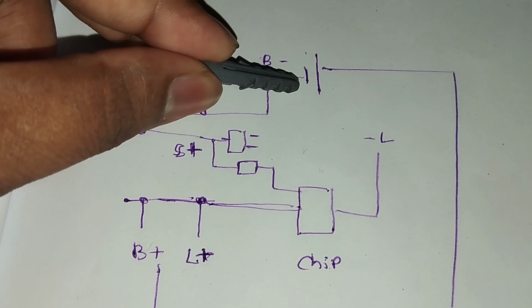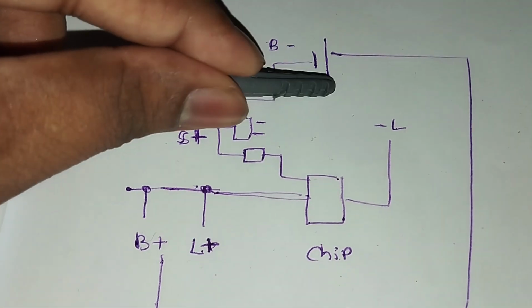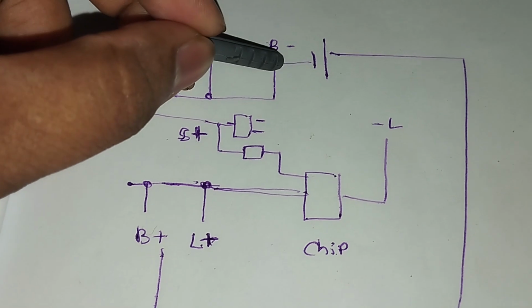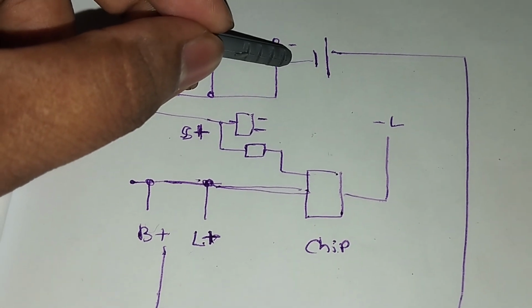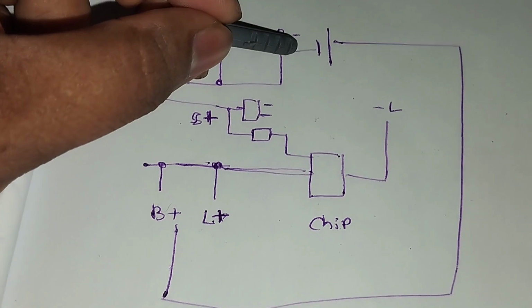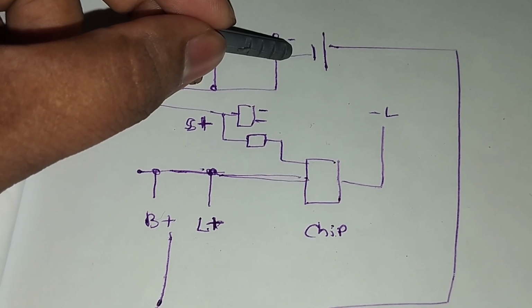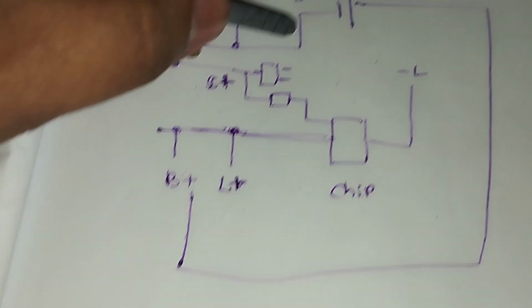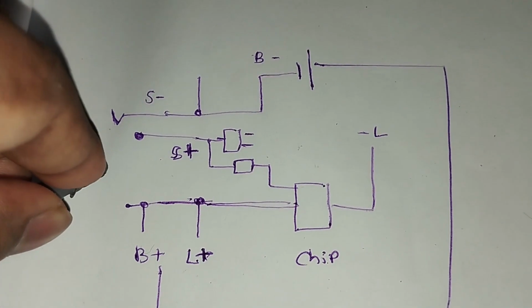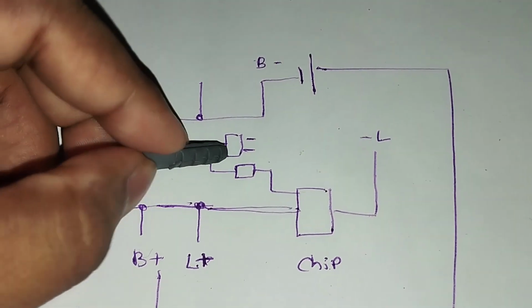So here is the basic functionality of our solar LED wall lamp. Then we have the 18650 battery that should be charged at 4.2 DC volts, and the maximum charging C rate is 1C charging, because that's the max charge. And here we have a DC 5.5 millimeter by 2.1 jack.